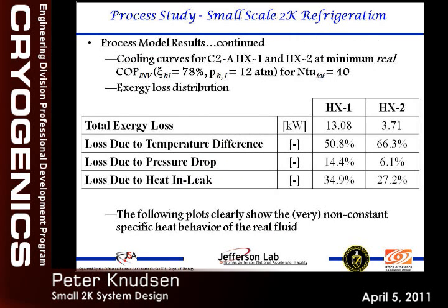Okay. So these are some more subtle, smaller issues related to that. In a heat exchanger, you basically have two components of losses. You have losses due to temperature difference and losses due to pressure drop. Those are two mechanisms where power, effectively input power, is being lost.